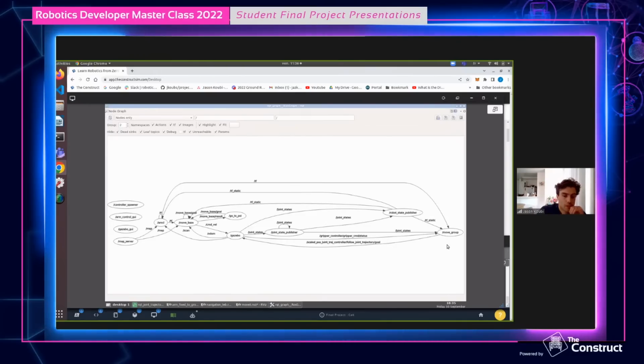It's not only the URDF of the arm, it also contains the rest of the robot. Yes, exactly. That's why it's automatically handled already, because MoveIt knows. But not for the table. Exactly, for the table it could crash. Did it happen? No. Lucky. I was setting an offset for the table height, for the Z position.